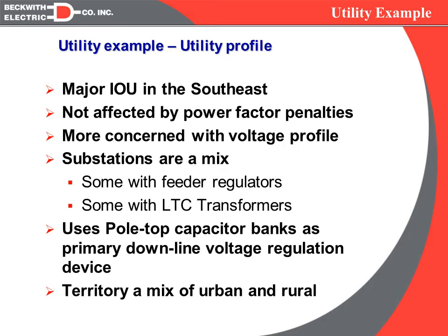Now, they have a mix of substations. They have some very urban areas which would typically have LTCs. And then they also have a lot of rural areas that would typically have longer feeder circuits and therefore would go with feeder regulation. But even in some of the more urban areas, their typical design now is to go with feeder regulation more so than LTCs.